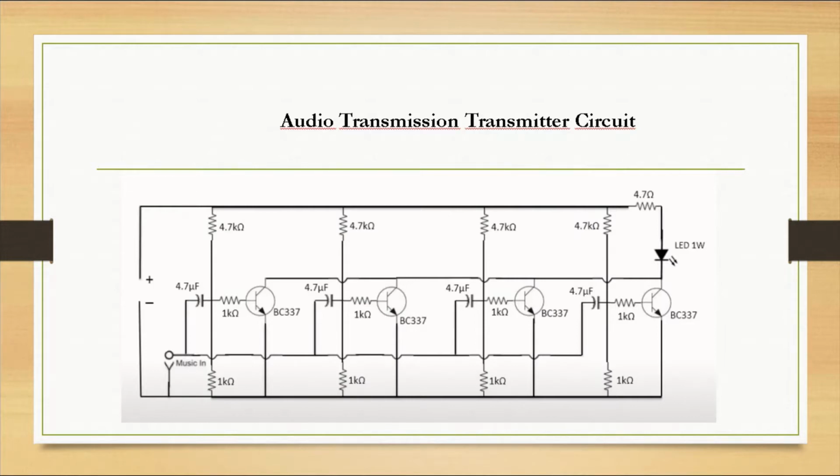A resistance capacitance coupled amplifier is basically a multi-stage amplifier circuit extensively used in electronic circuits. Here the individual stages of the amplifier are connected together using a resistor-capacitor combination, due to which it bears its name, RC coupled. The circuit shows such a 4-stage amplifier whose individual stages are nothing but common emitter amplifiers.